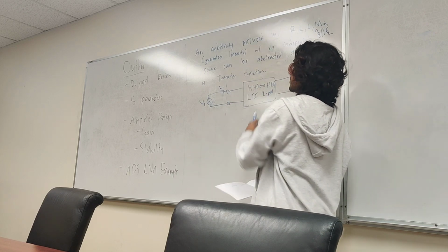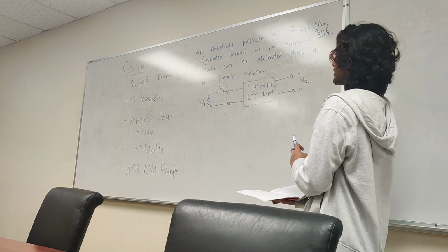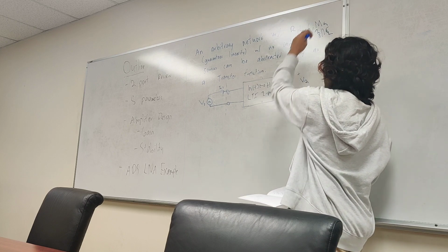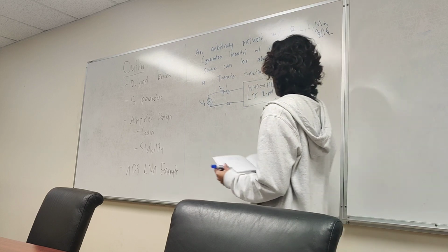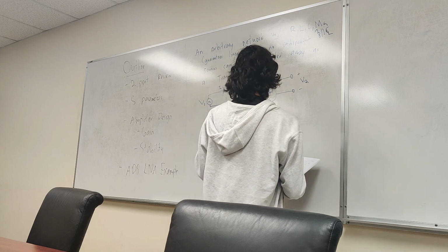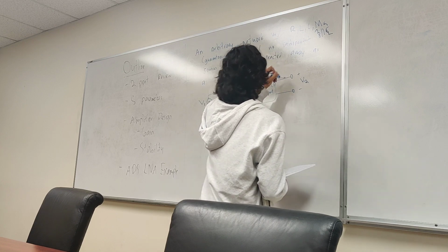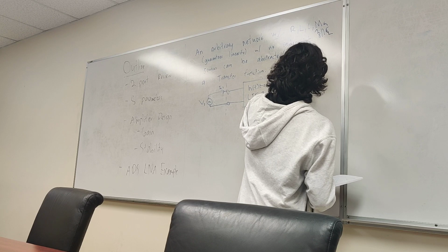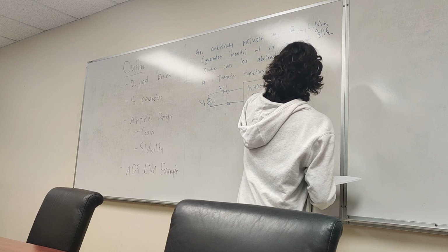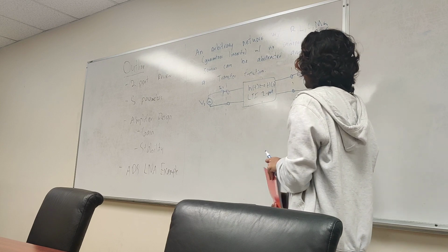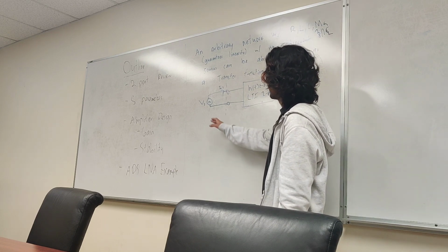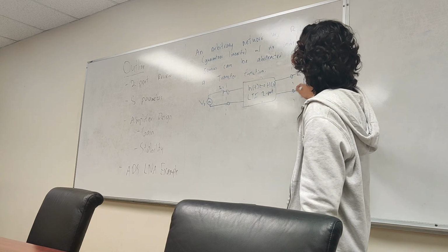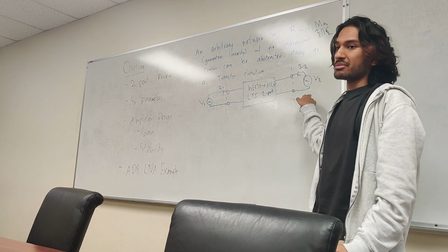At the end of the day, you want to abstract away any complicated circuit into very simple parameters that we can just plug and chug. Whatever's inside here, no matter how many R's, L's, or C's, get a nice little equation for it and call it a day. There's a few representations we can do. And let's just say something that looks like this. Now, this is technically, I wouldn't say illegal, but what I had before is you put in a V1, it's going to have an I1, and you can measure a corresponding V2. If you're trying to measure V2, that means you can't excite this port at the same time.